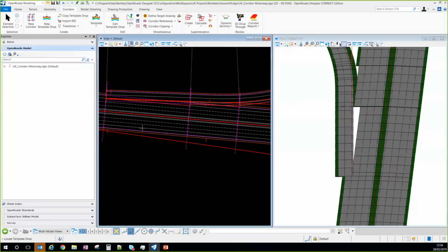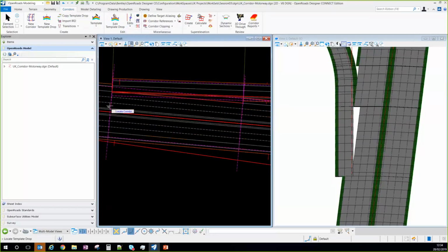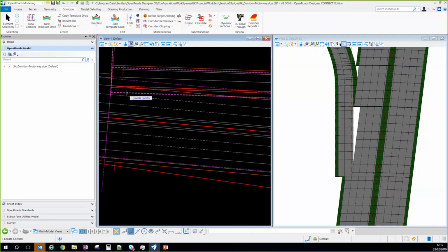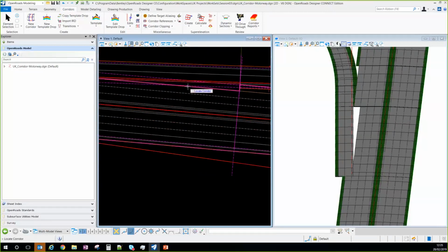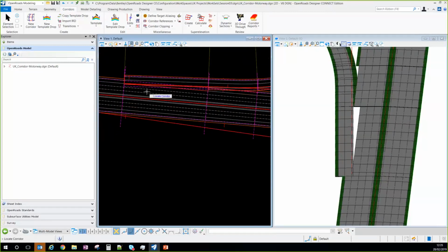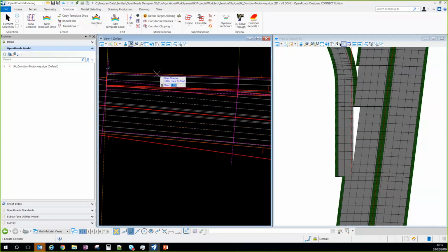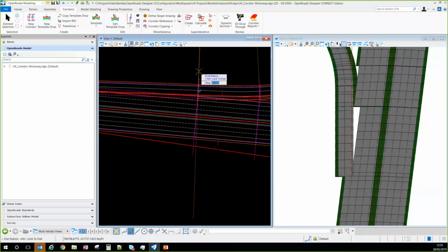Okay, now that the templates are okay, what we can use is the point control to direct the, I'll say, the hard strip point of the slip road and tie into the carriageway of the main line. So the first step is to select our corridor, the stations, so from 85 meters, so from tip to back. We can give it a name, so it will be nose.